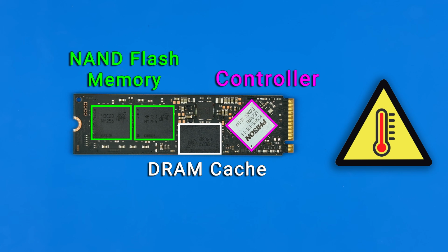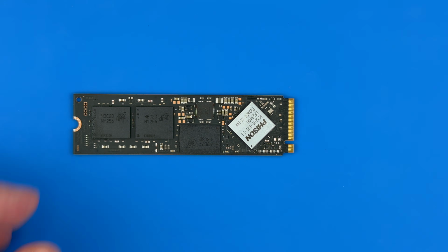High temperatures are a primary factor in the degradation of silicon chips. Prolonged exposure to elevated temperatures can lead to microcracks in metal layers and the deterioration of the dielectric between the layers of metal buses. Since both the memory chips and the controller are made of silicon with similar internal components, high temperatures adversely affect them.